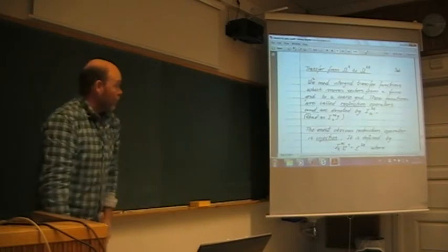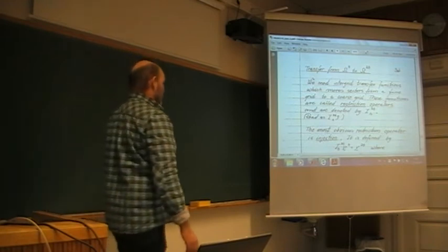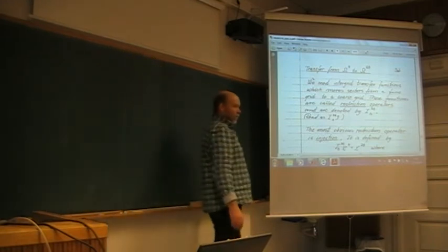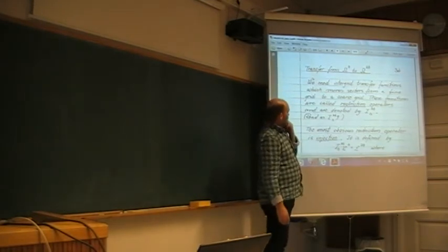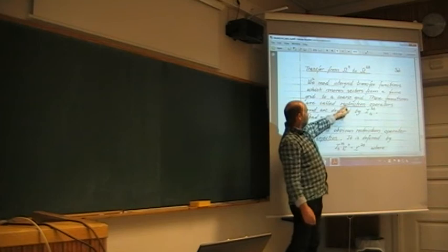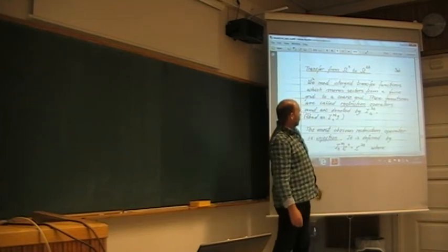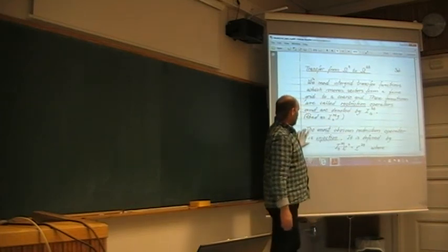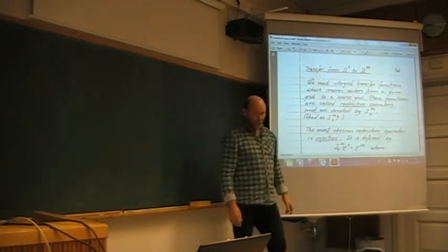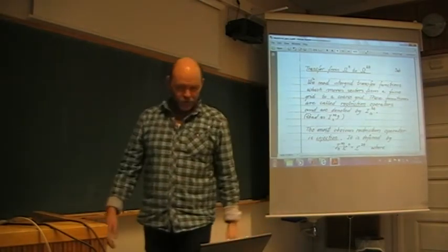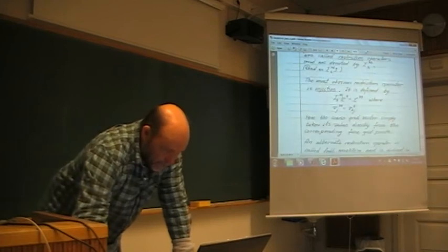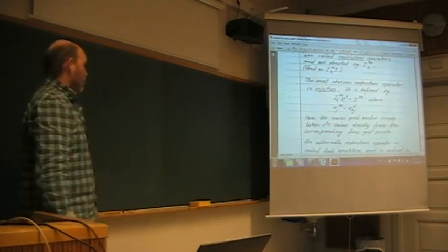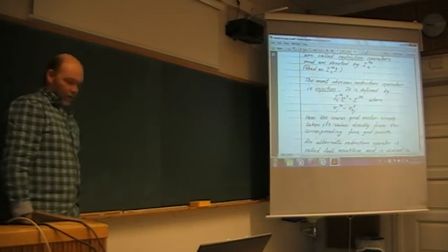So now going from fine to coarse, and here is where you could have some monkey business. So here you have to be careful. It's also called restriction, going from fine to coarse. The most obvious one, simple injection. You just take the points you have and you skip the ones you don't use on the coarse mesh. Very simple. Yes, that would be one way to do it.